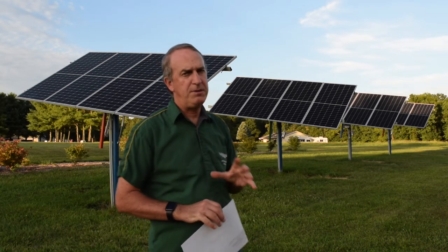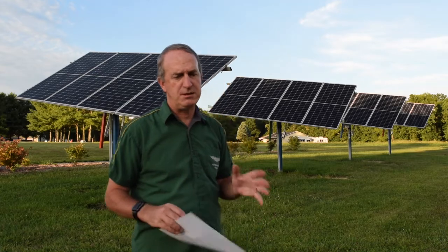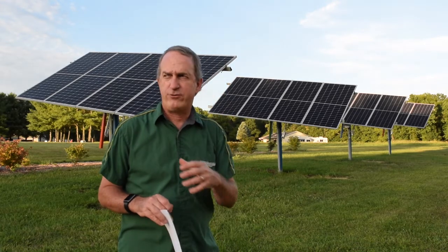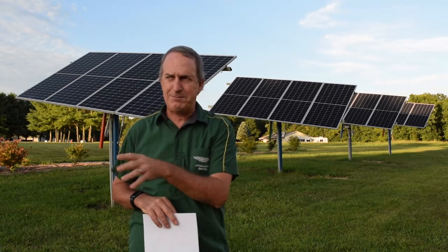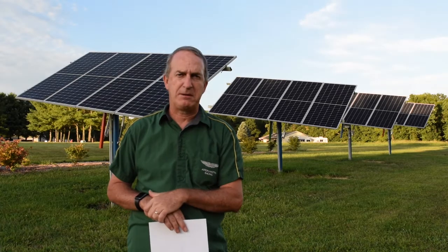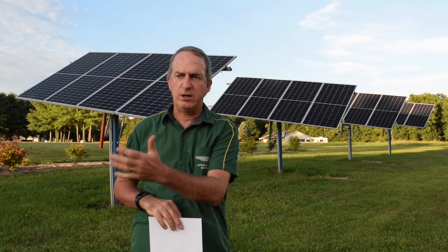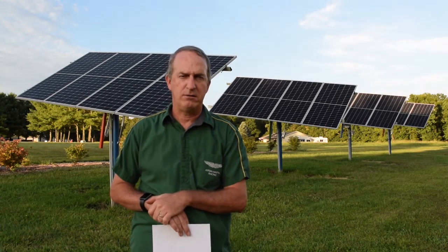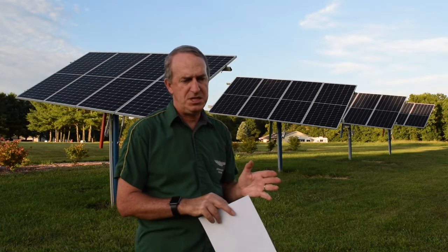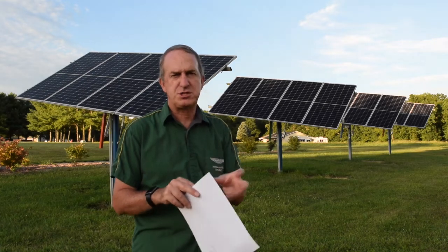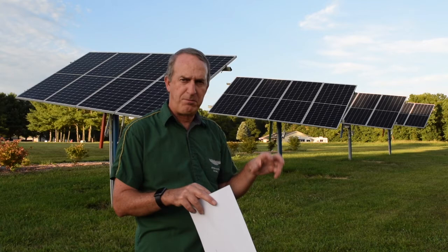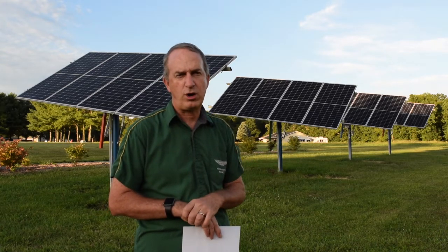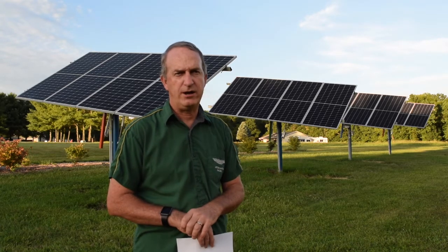And the big deal there is that in a Sunny Boy setup, the simple setup, if you've got shade on one of your panels, then the remaining panels are limited in their ability to make power, because they're kind of being held up by the one weak panel. The optimizer sees the weak panel, adjusts the voltage requirements of what it can handle, and then the other panels can do their full amount of work with an adjusted kind of plan.